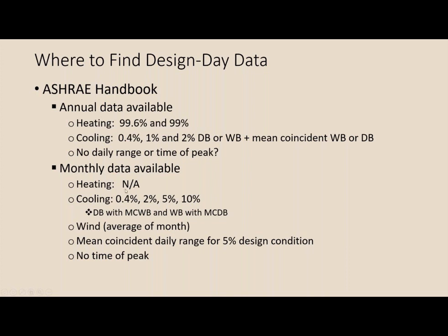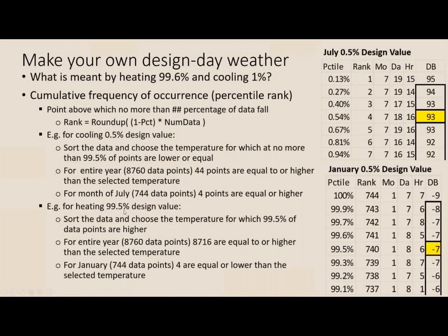In general, I think the main thing is to get reasonable design day data and to be aware, when you do your simulations, that if the sizing is coming out strange or you're not meeting loads, then it's worth going back and looking at your design day data, knowing that some of the things in that data could be off or maybe not realistic.